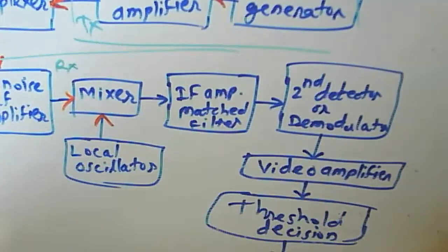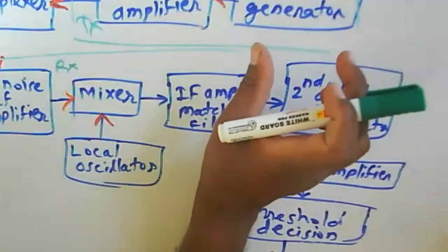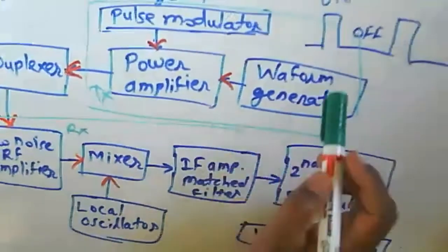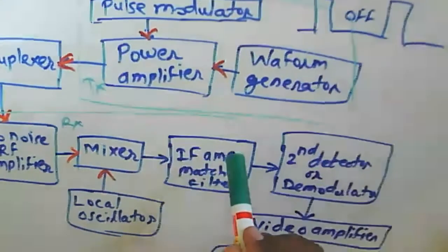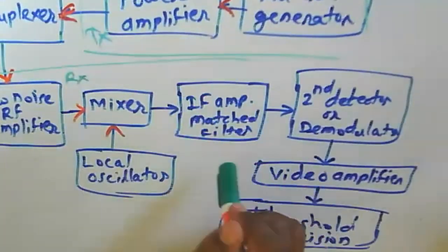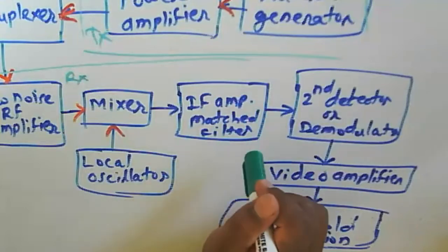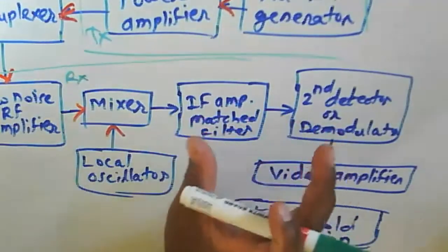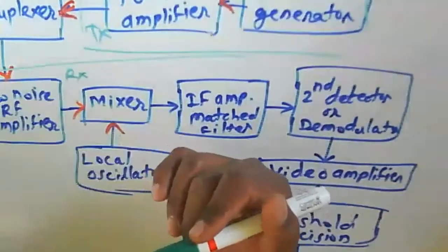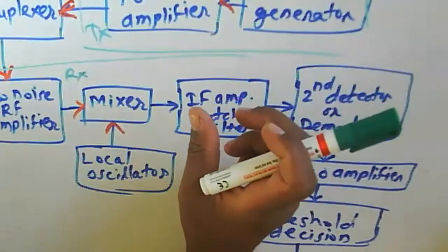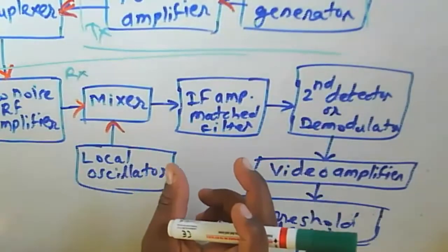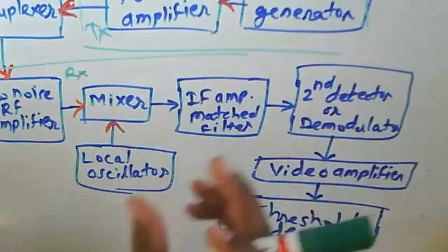But in the case of a signal, we say that a pulse is to be transmitted. So in that case, what will be the shape of the pulse? For example, we are saying that a pulse has a rectangular shape. So in that case, a matched filter is used to detect that particular shape of the pulse, or that particular pulse width of the given duration, because this is about the echo to be received. According to that, we can consider that the receiver bandwidth depends upon the pulse we are transmitting.